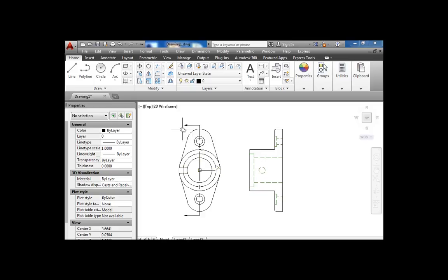However, what they want to do is put a cutting plane down through this. This line right here is your cutting plane, and anytime they cut down through here, this arrow signifies what you're looking at. When it turns to the right-hand side, you're going to see all the internal parts that have been cut down through here. This part on the right-hand side will be tossed away, and the only thing you'll see is the left-hand side and just the parts that have been cut.